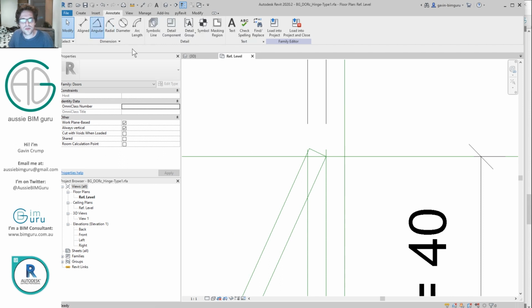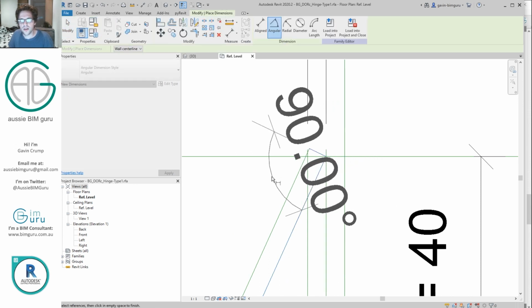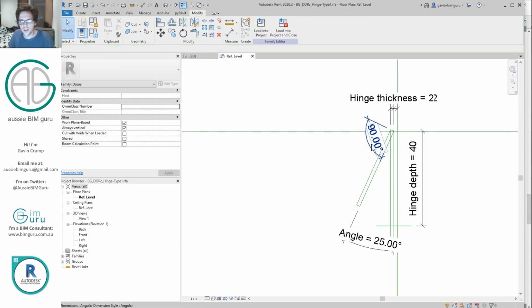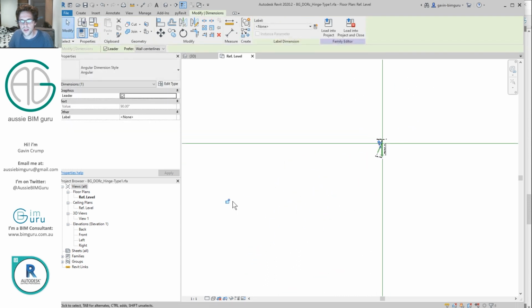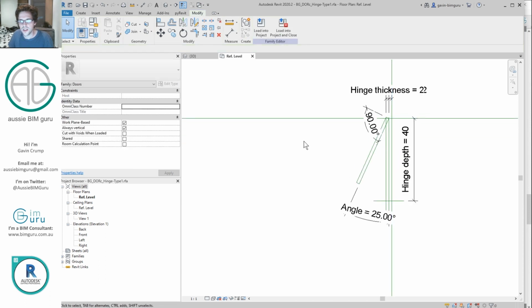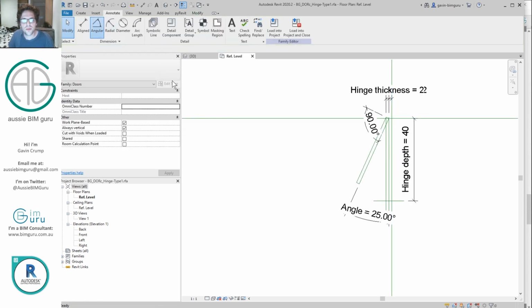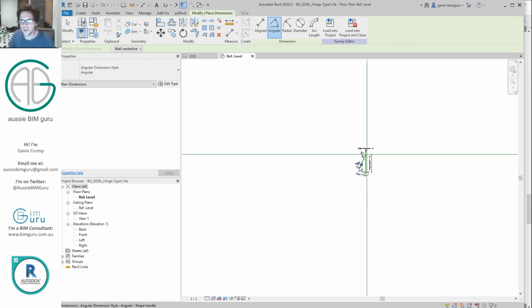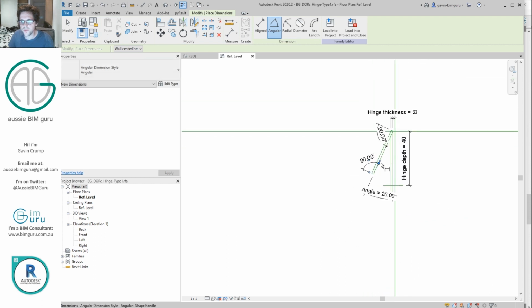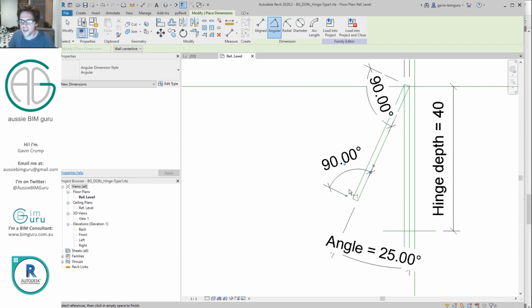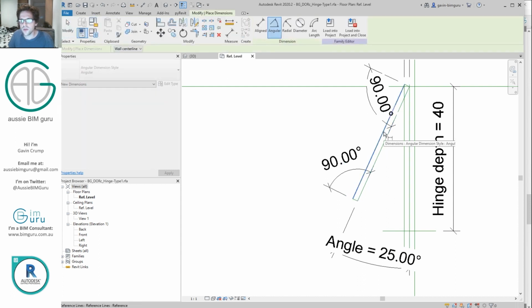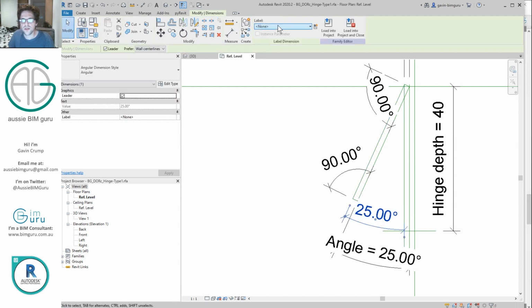So what I'm going to do first is create an angle between those two reference lines, set to 90. And in this case, I'm going to lock it. Sometimes it can be quite far away for some reason. I do find angle constraints have very strange behavior sometimes. And I'll lock that one. So we've essentially created a 90-degree relationship. I also need to take an angle between here and the same reference and constrain that to the angle as well.